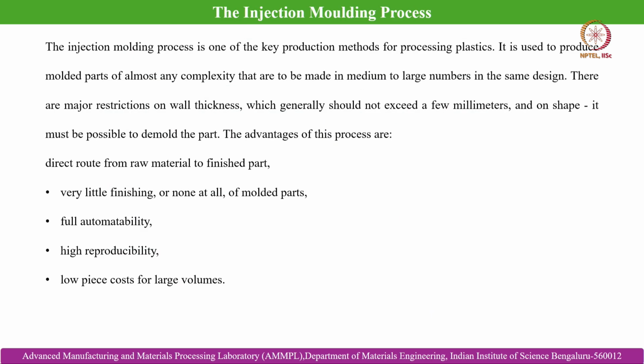Okay. So, then we will continue. Now we have briefed about some special powder metallurgy processes. Out of that, as I told you earlier, injection molding is a process where we can develop near net shape parts with great precision, and also net shape parts without any need of post finishing, such as machining or polishing processes.